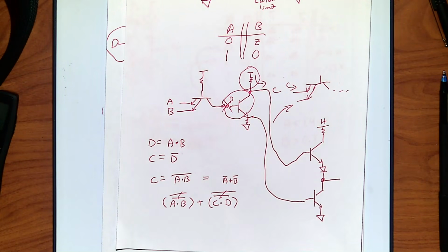And you've now just walked through. The trick with analyzing all of these is just look at each transistor gate separately, and then just cascade the effects. Once you figure out each one, it doesn't matter the order you figure them out, right? They're either 0 or 1, right? And then just left to right combine them, and you'll actually build up anything that's in there.